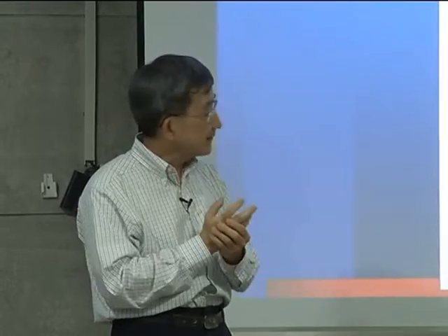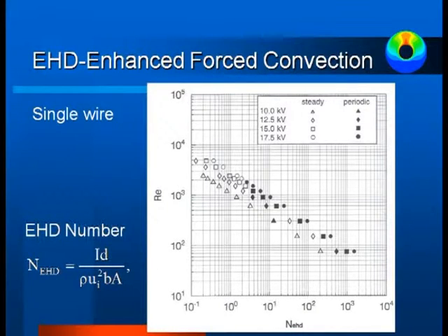After I found that, I let my code run to that time, and then I could completely reproduce the result. But because he terminated the computation prematurely, he missed a very important physical phenomenon: the flow goes from steady to oscillatory. You may think, so what? But if the flow becomes oscillatory, it has a very important application because it can enhance heat transfer.